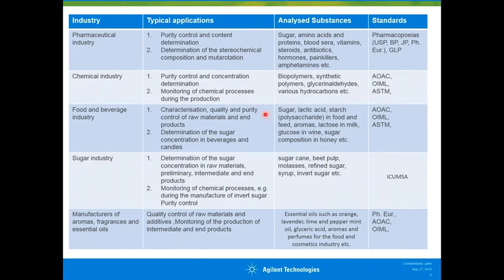Now let's discuss applications for the polarimeter. Generally, it is used in quality control, to determine purity of pharmaceuticals, sugar, and starch-based products. There are several applications in QC. Temperature controlled polarimeters can also be used to determine some gelling behaviors. Most importantly, since the samples are not destroyed by this technique, it can easily be used to measure the purity of expensive raw materials, such as essential oils and in perfume production.